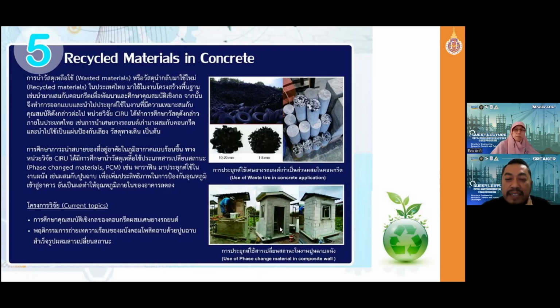Because I did this, I monitored it for 1 month in April, because April is the hottest month in Thailand. So I put the AC inside and I have an electricity meter. I continually measured and compared the one with the conventional plaster against the one with plaster that includes phase change material. The one with the phase change material can prevent the energy loss better and could also save you money on your electricity charge.